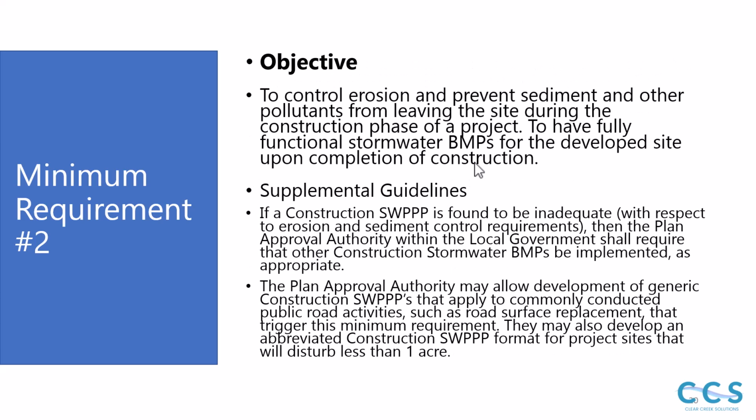The objective is to control erosion and prevent sediment and other pollutants from leaving the site during the construction phase of a project, and to have fully functional stormwater BMPs for the developed site upon the completion of construction. Some supplemental guidelines: if a construction plan is found to be inadequate, then the plan approval authority within the government shall require that the construction stormwater BMPs be implemented as appropriate.